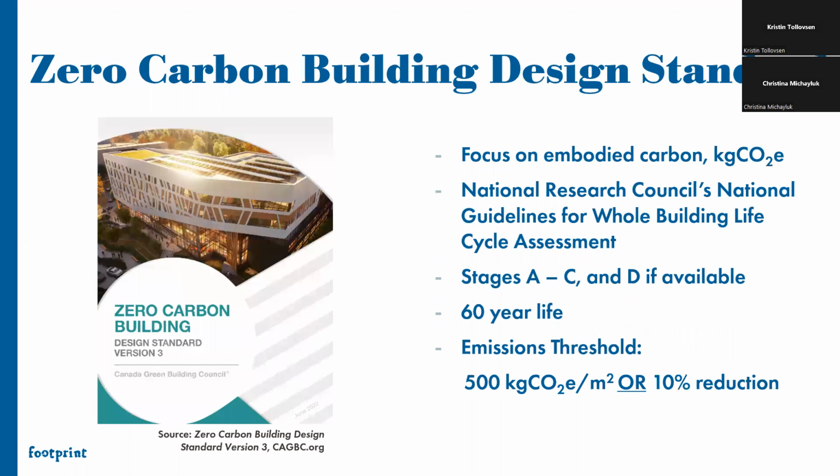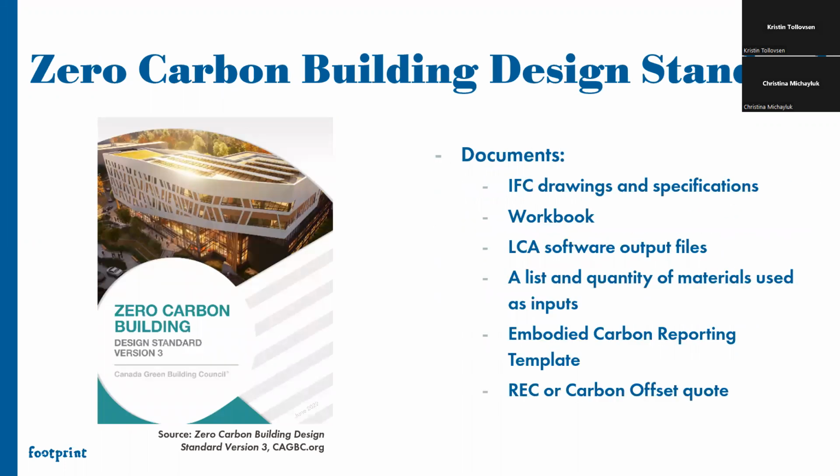But going to the Zero Carbon Standard and what's required there. The life cycle assessment is just one part of the total standard. There are a number of other items that would need to go in here, but the workbook has a section for embodied carbon that needs to be completed. The IFC set drawings, or the drawing set being used for the submission, and specifications would also be included. They also want your LCA software output files. Depending on what program you're using, this may not be applicable.